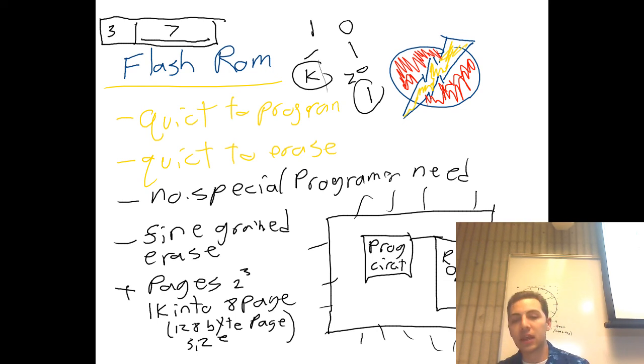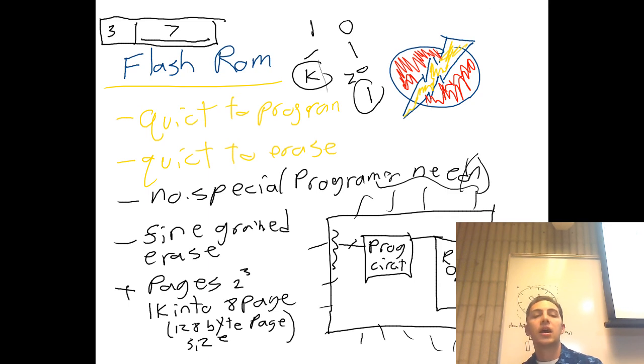There would usually be some set of control signals that go to that programming circuit, or writing to certain addresses in a certain sequence, almost like a secret decoder knock. If you write to certain memory locations or read from certain memory locations in a certain order, that activates the programming circuit. Or it might just have an extra interface associated with it. And this would still have your K address lines, your N data lines.